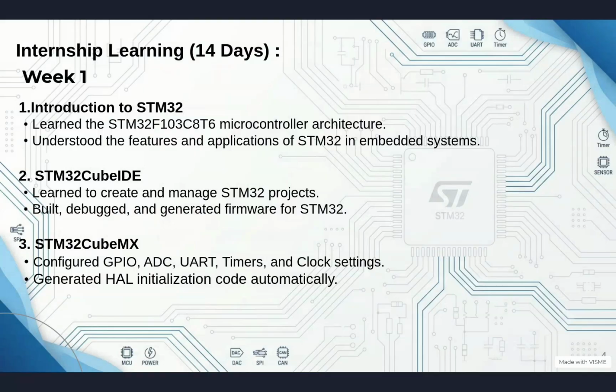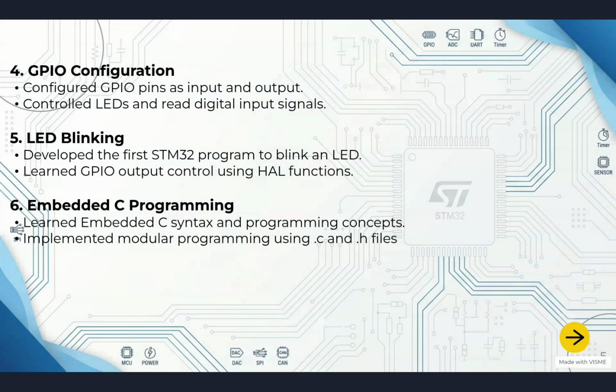In STM32CubeIDE, we learned how to create an STM32 project, write embedded C code, compile the program, fix errors and generate firmware files. In STM32CubeMX, we configured GPIO, ADC, UART, timer and clock settings, which automatically generates the initialization code.